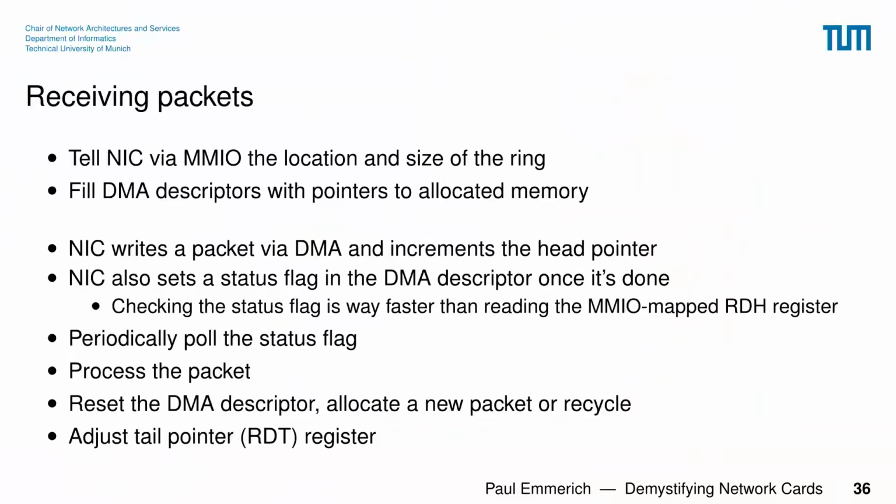Next step is we periodically poll the status flag. This is the point where interrupts might come in useful. There's some misconception. People sometimes believe that if you receive a packet, then you get an interrupt, and the interrupt somehow magically contains the packet. No, it doesn't. The interrupt just contains the information that there is a new packet. After the interrupt, you would have to poll the status flag anyways. So we now have the packet.